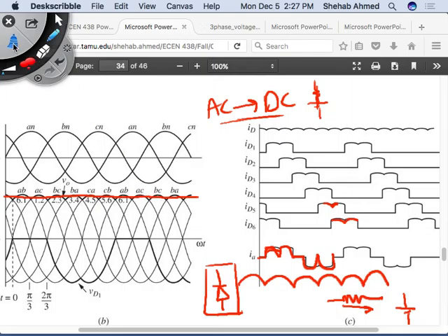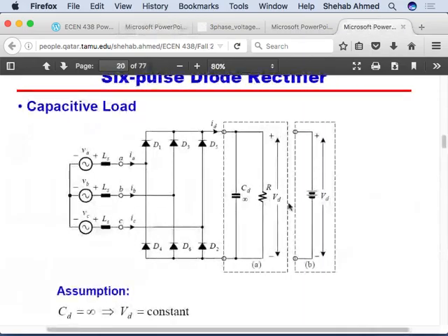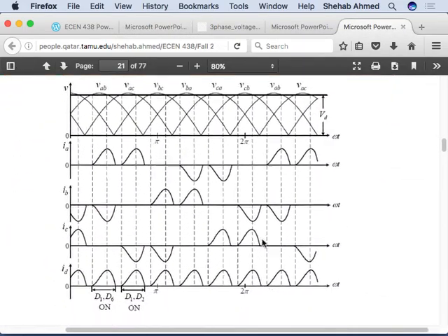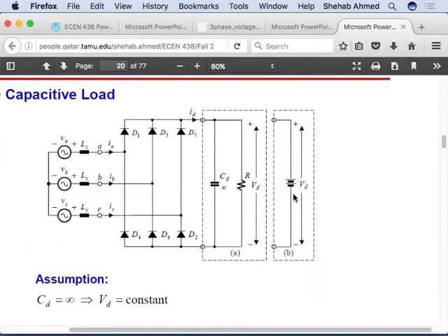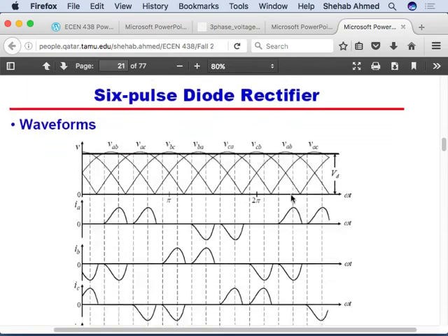It's just a waveform that they had drawn here, and I didn't show you before. Like this is phase A current, phase B current, phase C current. Instead of these two humps being up high, they added a DC source here. If you add a DC source, what happens? You're reducing the current. You're opposing the current coming from your input rectifier, basically. I'm just showing you some pictures of some interesting waveforms, having a discussion here.